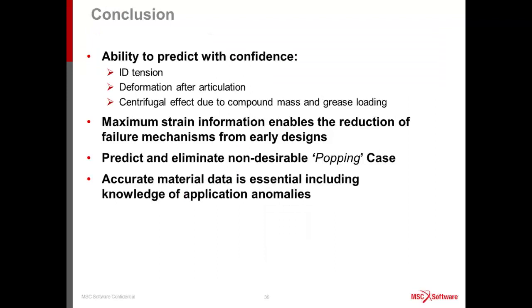So in conclusion, on the CV boot analysis, it allows us to predict with a very high degree of confidence the ID tension, so we don't need to use tie wraps and retention clips. We can rely on the force produced by installation alone. It allows us to predict the deformation after articulation, which we can supply to our customers and allow them to do airflow analysis. Or we can also look at the centrifugal effects from the mass of the component itself, as well as the grease loading, which can be very important in some high-speed applications. By monitoring the strain information, we can reduce failure mechanisms again from the very early design stage. And it allows us to run through designs in a virtual environment rather than making tooling and testing.